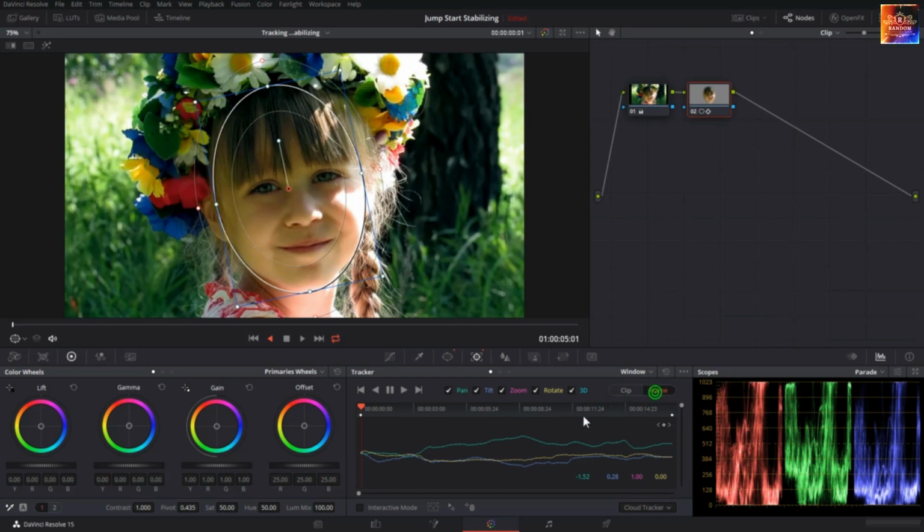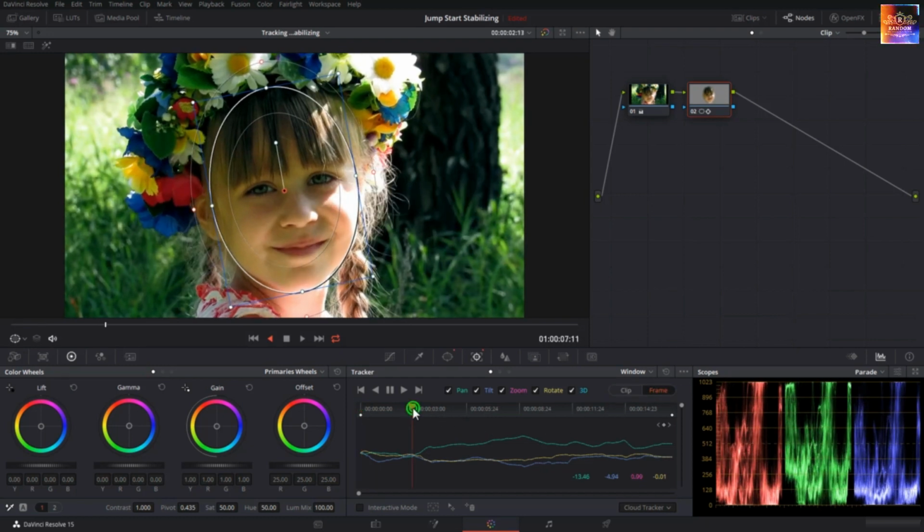But if you are in the frame mode, that's going to be interesting. Let's come over here, for example, at 3 seconds and decide that you want to shrink or rotate it a bit. So I will rotate it just like this randomly, it doesn't matter. And I will shrink it a bit. Now, the changes that you have done here are keyframed. You can see a keyframe over here. You have a keyframe in the beginning, keyframe at the end, and you have this keyframe here.